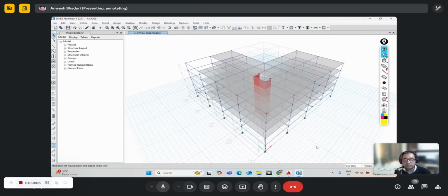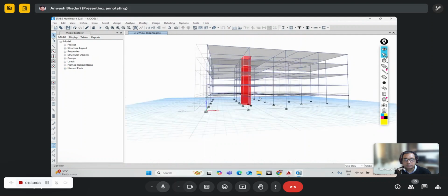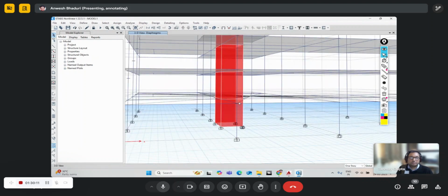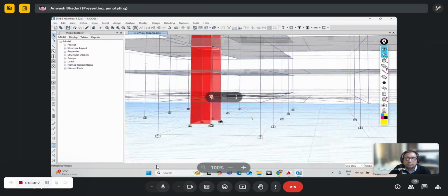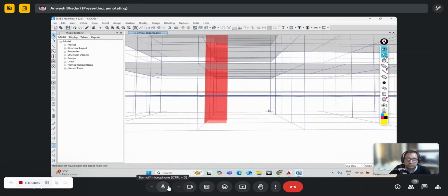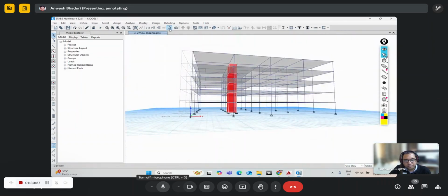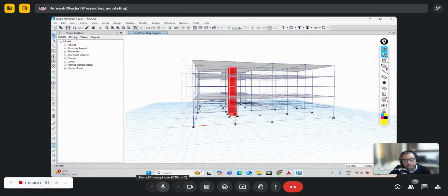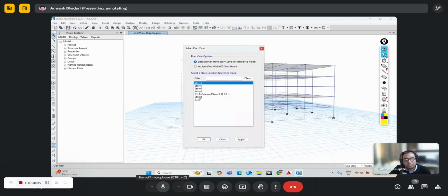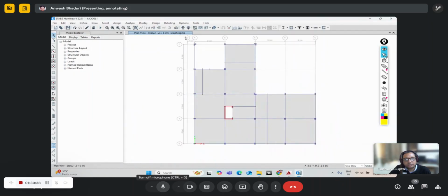Now assigning these diaphragms to joints, there is one risk of sometimes selecting a joint which is in some other level. So this needs to be checked with the utmost care whether there are some joints in some other level or not. In that case, the program will show an error. No, so we have checked there are no problems as such. Now we'll go to story two. We'll select here.